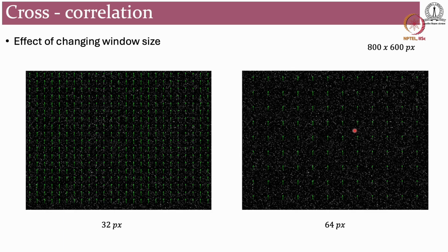We normally use lasers, which is not strictly necessary, but we use them, and the intensity and the depth of the laser should be well known beforehand, so that your particles are well lit and you can get such good vectors without much noise, right?